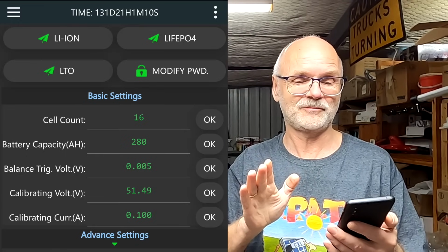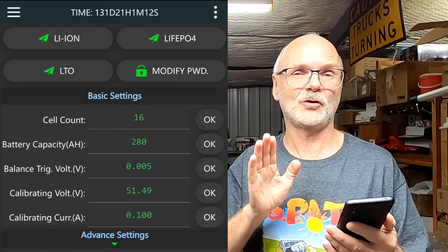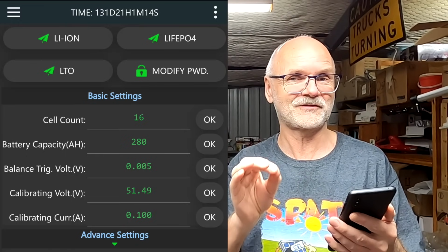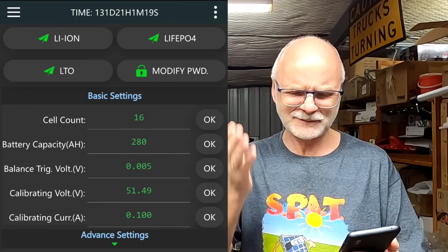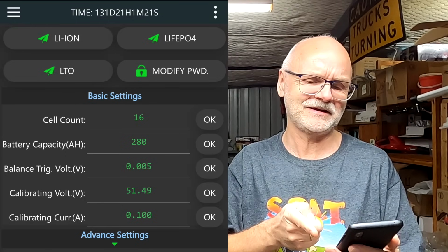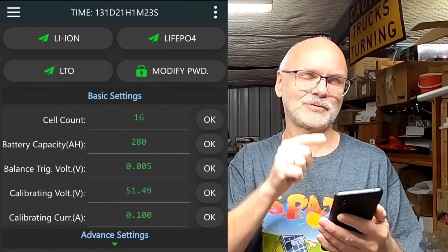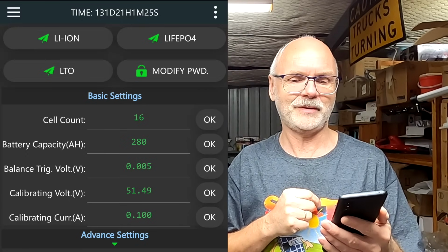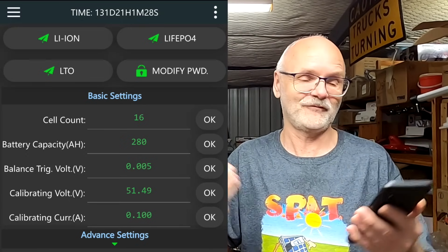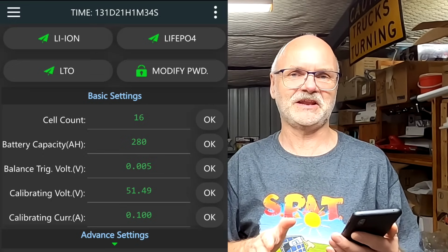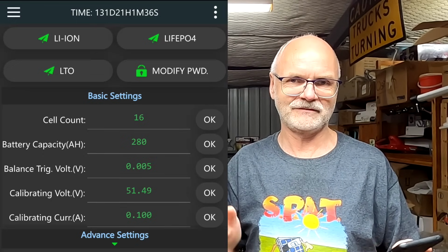Never ever do this afterwards, because it will override all your settings with the default settings for this profile. I've done this multiple times and I said, well, I'm sure I have changed these settings here. But in the meanwhile, I pressed the lithium iron phosphate button again, because I thought, well, why not, you know? Tell the BMS what you have. And it overrode all my settings again, so I had to do everything again.